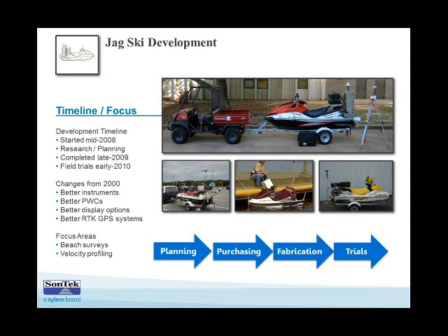So we would always, and we still do, have to install and survey in a tide gauge and then take our depth measurements and the local tide and get those all resolved and interpolated in time and space after the fact and get it back to a consistent vertical datum that could be used often in the future for analysis and surveying purposes. And that's gotten a lot easier now with HydroSurveyor. There's a lot less work to do on the backside, that's for sure.